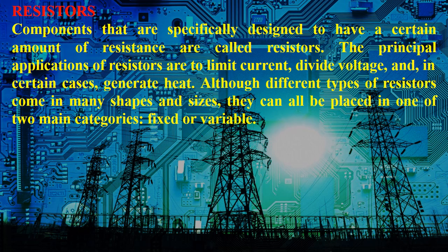Okay, now let's look at resistors. What are resistors? What's the difference between resistors and resistance? Resistance is an internal property of a conductor. Resistors are the components that are made. Resistance is the property of a material through which current is flowing, and resistors are constructed to control current and voltage in a circuit. So components that are specifically designed to have a certain amount of resistance are called resistors. The principal applications of resistors are to limit current, divide voltage, and in certain cases generate heat.